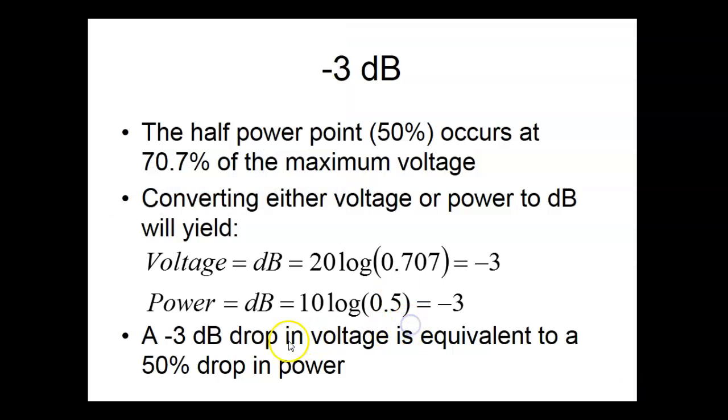So a 0.5, if I'm measuring power, then 0.5 is equal to minus 3 dB. That's half. If I'm doing voltage, 0.707, I take the log of that and multiply it by 20, it gives me a minus 3 dB power gain. So what we're saying is this formula right here gives me an idea of the power gain I've got in a circuit measuring voltage. I don't have to measure two different things. Y'all understand? But the only thing we got to know is the maximum voltage I get out. And when it drops down to minus 3 dB, which is 70.7% voltage, then that's what we call the bandwidth. Because if the voltage drops down 70.7%, the power drops down 50%. The power has dropped down 50%.